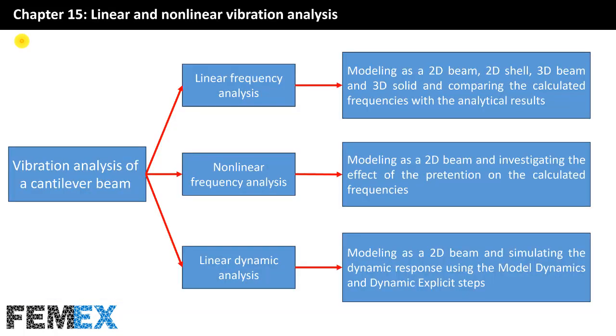Chapter 15 is about linear and nonlinear vibration analysis. In this chapter, I have analyzed the vibration of a cantilever beam. I have done 3 different procedures: linear frequency analysis, nonlinear frequency analysis, and finally linear dynamic analysis. In the first procedure, I have modeled the cantilever beam as a 2D beam, 2D shell, 3D beam, and 3D solid, and I have compared the calculated frequencies with the analytical results.